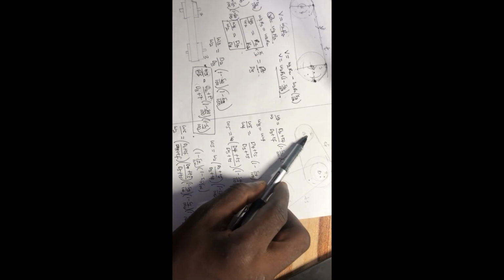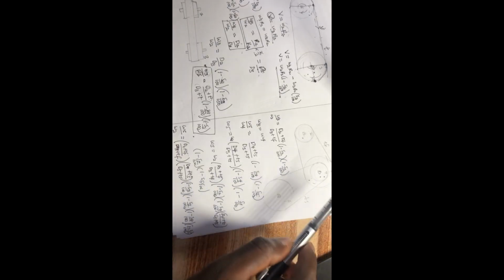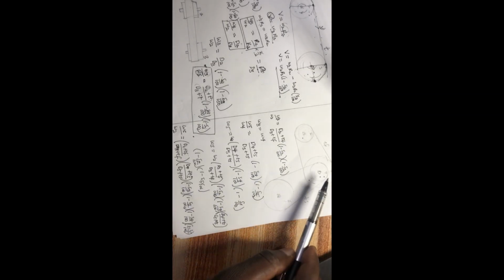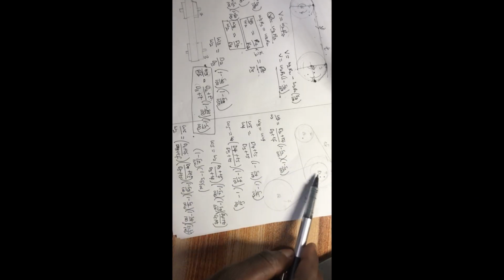If it has slip, you multiply the ratio D2 on D3 multiplying D4 on D5 by the slip factors of 2 and 3. If it were just the 2, that would have ended it. But here you have another one, so driver on driven, driver on driven. So you have this general equation. In the next video, we are going to solve some questions using this.